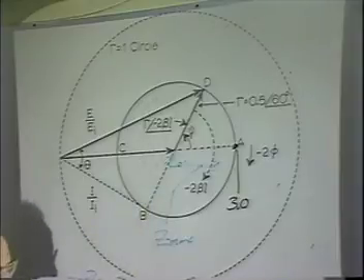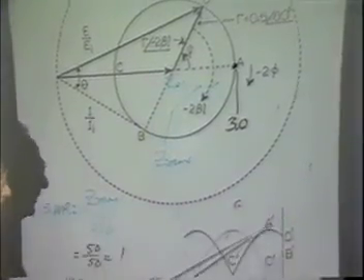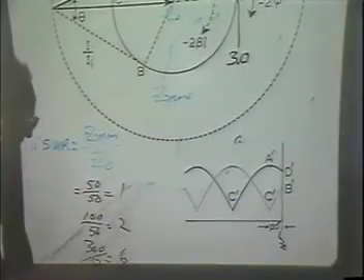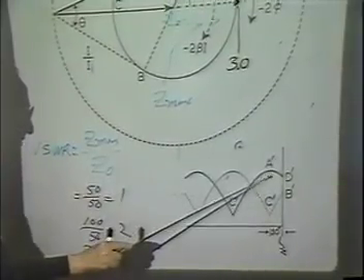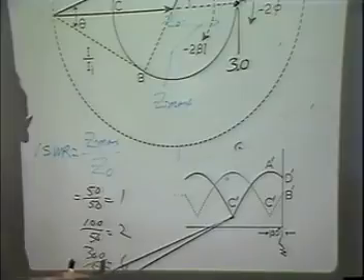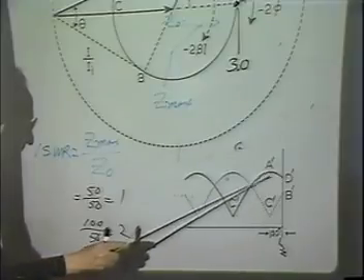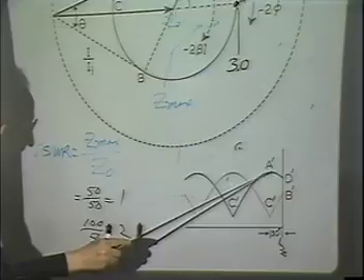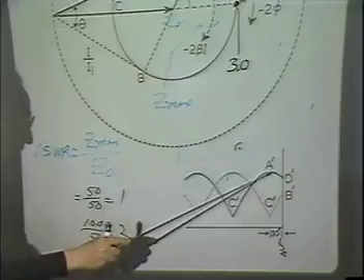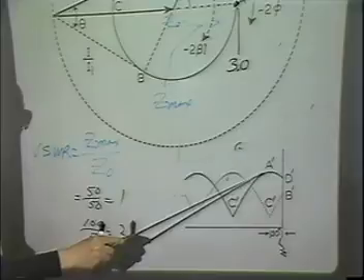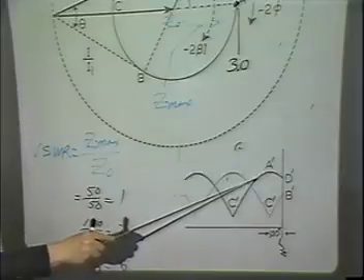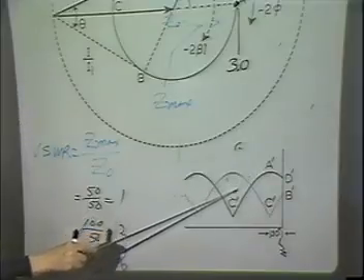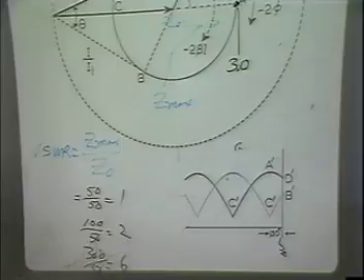If I looked at this, this would be 150 ohms in this case. If I look down here, it would be 17.5 ohms. Someplace in between here, it'll hit 50 minus jX. But anyway, here you'll start out with, in this case, 150 ohms, then it'll go to 149 minus j something, 140 minus j, on down until it gets to a pure resistance of 17.5 ohms, I think we calculated.